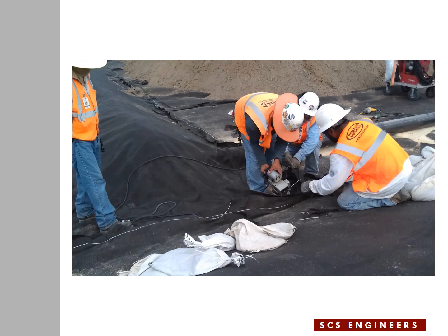In this slide, it shows that they have completed the LCS pipe, completely embedded in gravel, and geotextile is pulled over it. The crew is sewing the geotextile in order to close the textile completely. And then behind the crew you see the pipe, which is a solid pipe bringing vacuum to the gravel. The pipe would have to penetrate the geotextile and terminate in the gravel bedding around the LCS pipe.